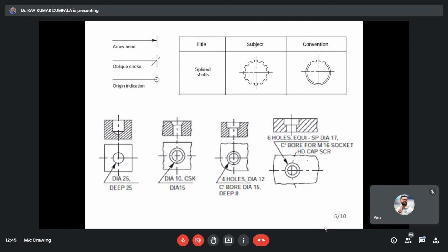We'll be studying these conventions. Just for your idea, I'm showing those things. Mostly you'll be using this arrowhead everywhere. Everyone, please don't draw any other arrowheads. Even in the books or conventions, they may show different indications to represent an arrow, single lines, double lines, or whatever it is. Don't use any of those things. Use only the filled arrowhead. Please use only this one.